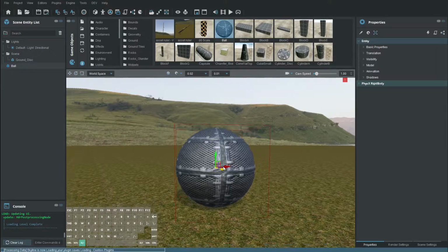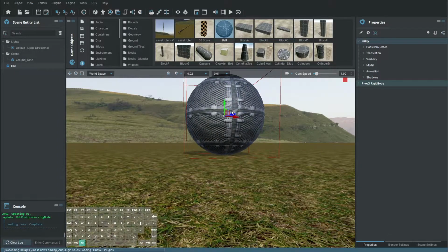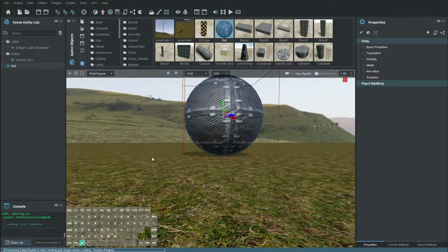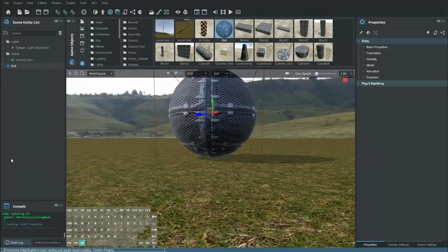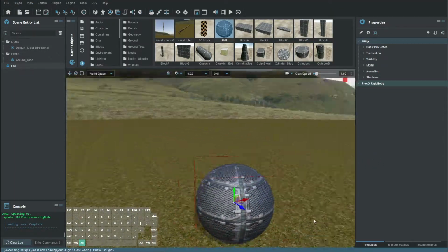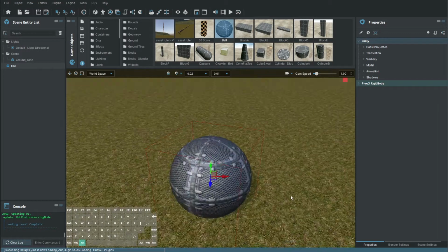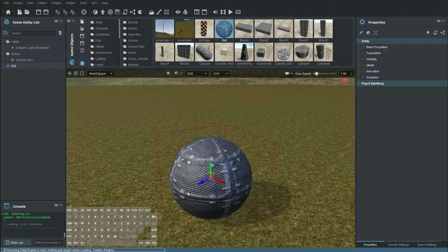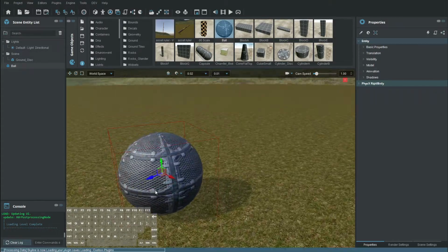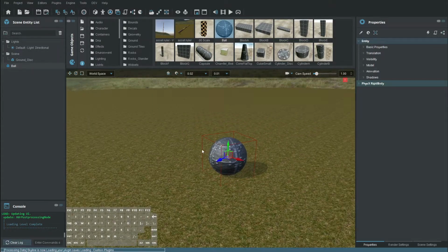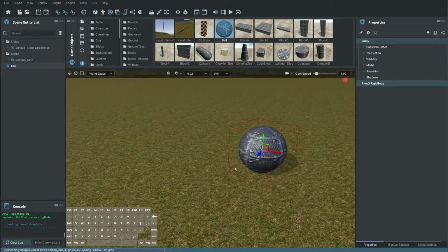Now a little tip, if you've got Alt pressed, you can actually use the middle mouse button and keep an orbit, say, at the bottom, or drag down and show the orbit at the top. Release the Alt key and press again and the orbit's reset. And also, without Alt pressed, we can still pan the scene. Here's a handy tip. Okay, let's move that over there.